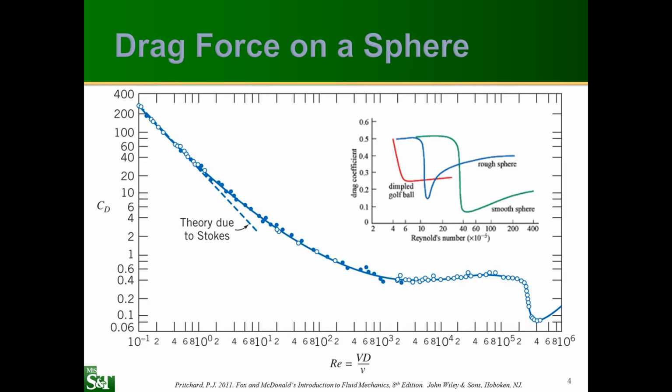This transition to turbulence can also stabilize local fluctuations. As an example, we can look at a knuckleball in baseball. Now, when the knuckleball is thrown, the boundary layer is laminar. However, the laces on the baseball represent roughness elements, and as the knuckleball very slowly rotates, those roughness elements trip the boundary layer to turbulence at a location that varies with time. So as the ball is flying, it has this very unpredictable transition to turbulence.